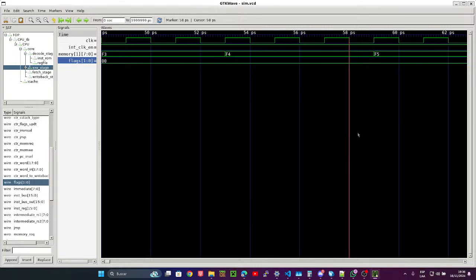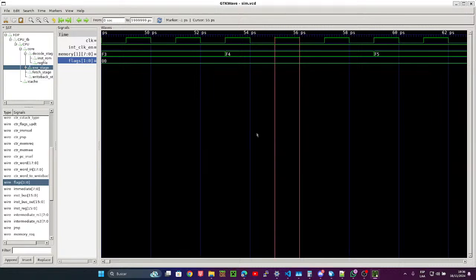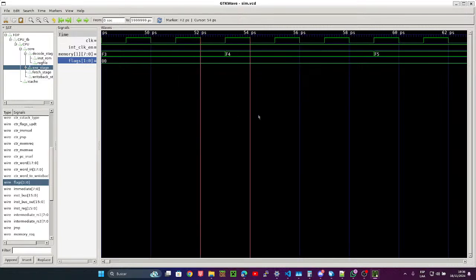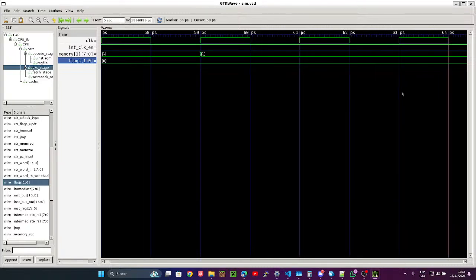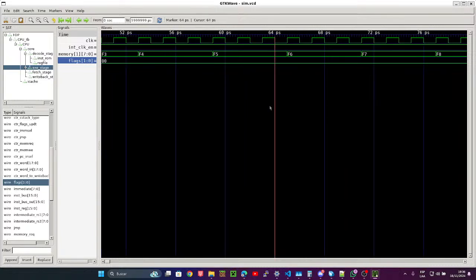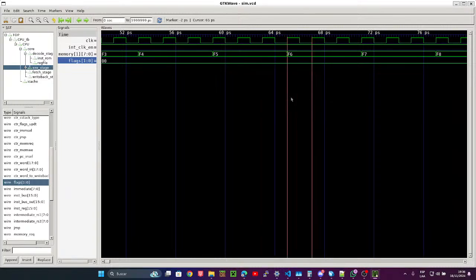Oh. That's not common, because usually when you have these outputs, you don't have the transistor pulling it high. You have the transistor pulling it low. So the 1 becomes the recessive state and is controlled by the pull-up resistor, and the 0 is active. And that's called open drain, open collector, depending on your technology.